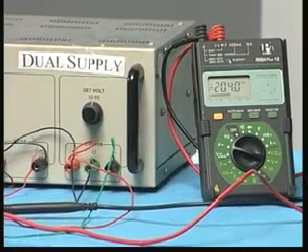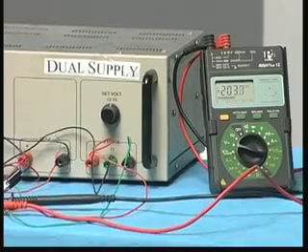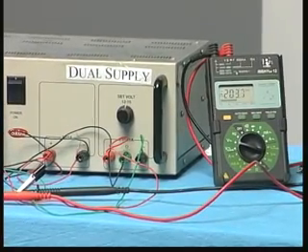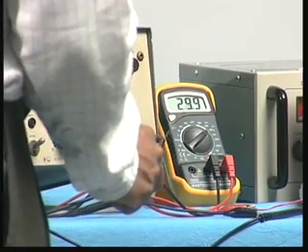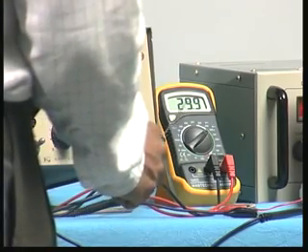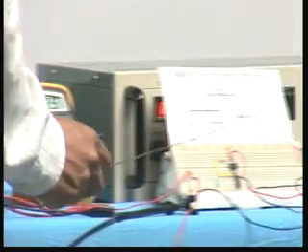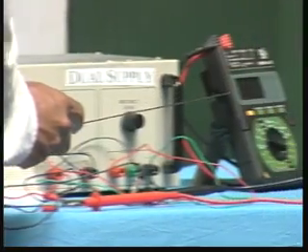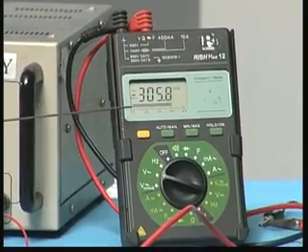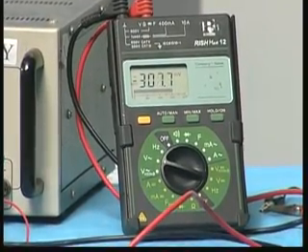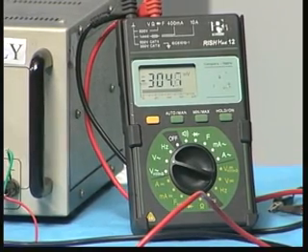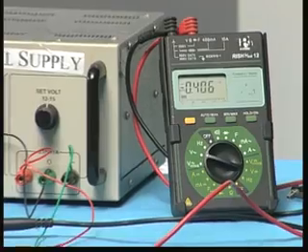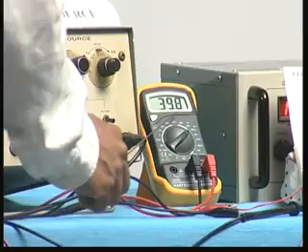You can see that. Now I am going to increase the current from 20 to 30 microamperes. You can see this current meter reads 29.9, which is close to 30 microamperes, and correspondingly if you now observe the output voltage, it will be very close to 300 millivolts. Now I keep moving to another current, 40 microamperes, 39.8 is the reading here.